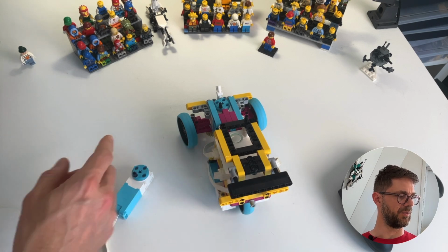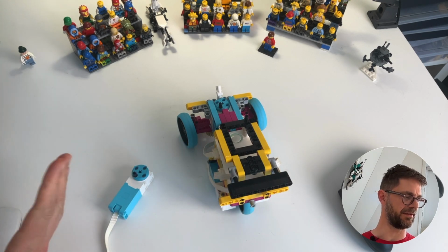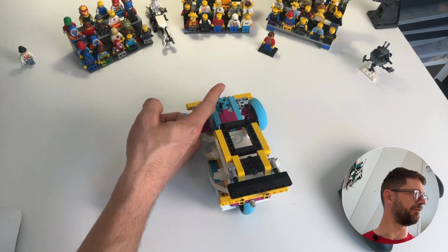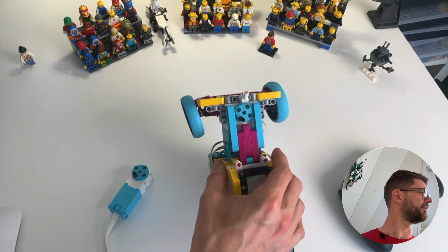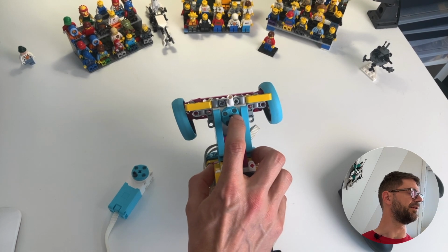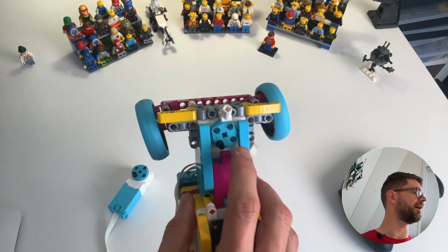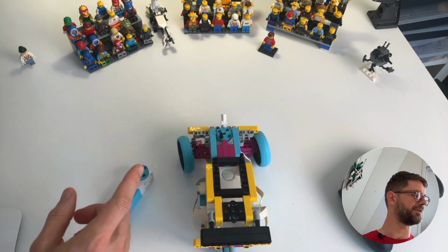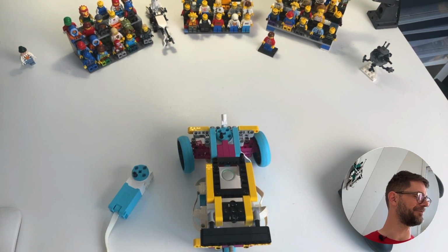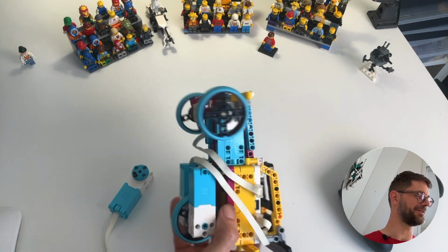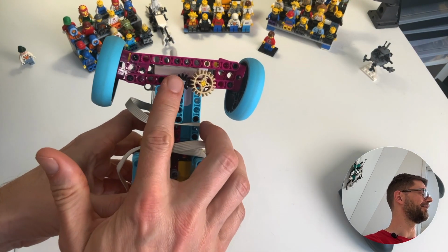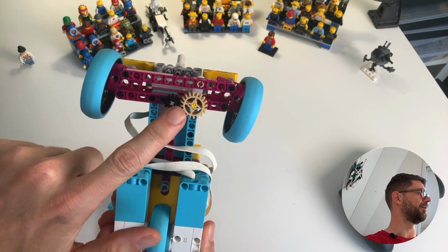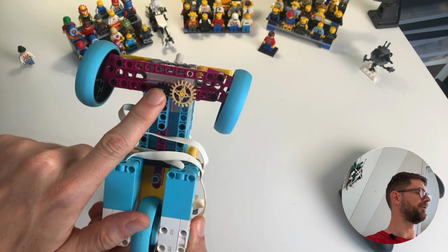Okay. And what we see now is that our program works. The motor goes to our position of 30. You can see that here. So the faint gray line is at 30 degrees, but our wheels moved in the opposite direction for less than 30 degrees. That's because, again, there is a gearing here, and the gearing is a 20-tooth gear and a 12-tooth gear.